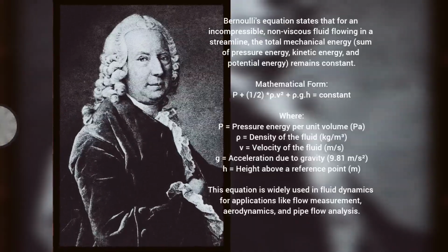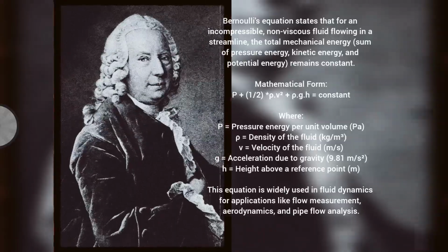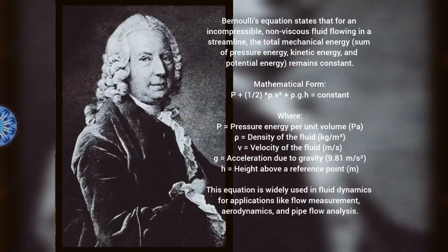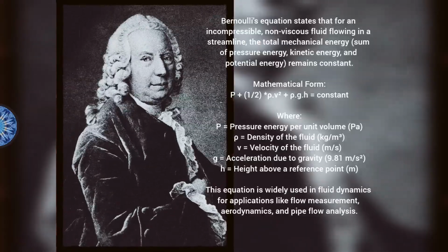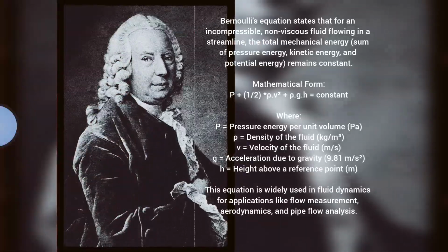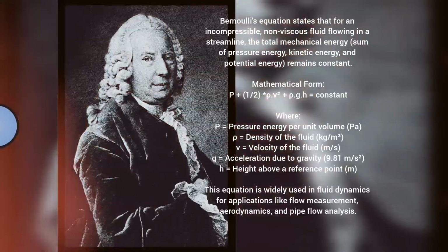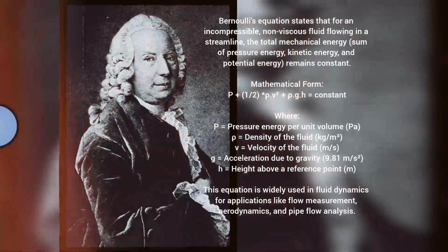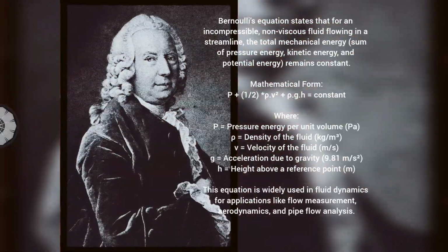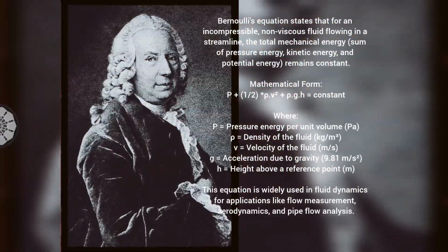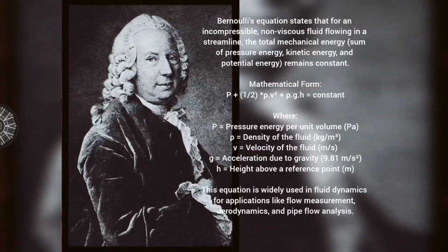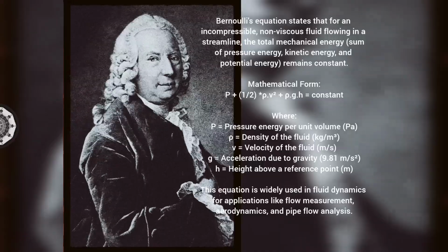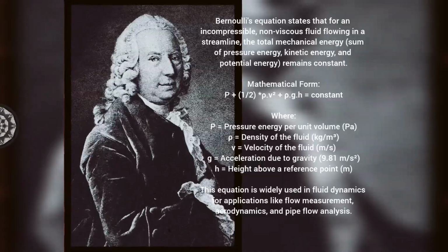Pretty much. But the interviewer threw in a twist, bringing up that real-world fluids always have some viscosity. Right, because we don't live in a perfect physics textbook, unfortunately. Exactly. And that's where things get really interesting. The interviewer asked, how would you deal with that viscosity in real-world applications? Ooh, putting them on the spot. So how did the candidate handle that? Honestly, pretty well. They brought up the idea of head loss. Head loss. Yeah, it's represented by HL in the equation. Basically, it's the energy that gets lost due to friction as the fluid's flowing. So some energy is leaking out of the system because of that friction.